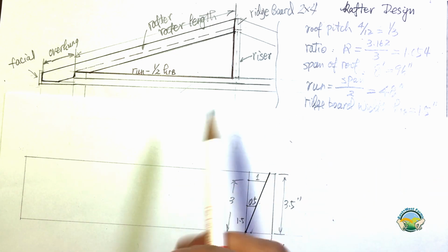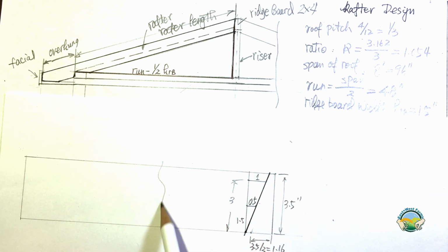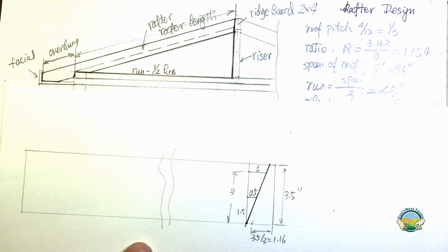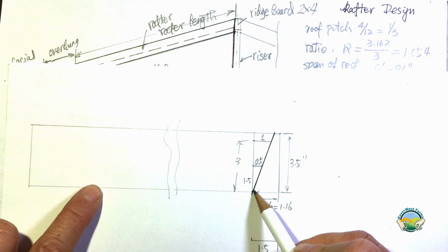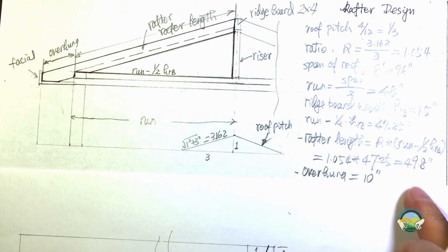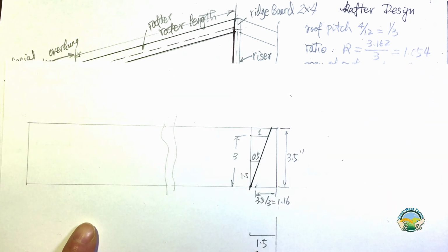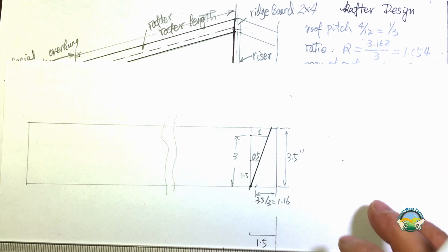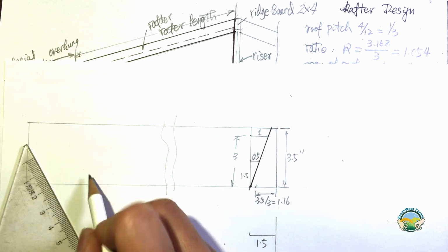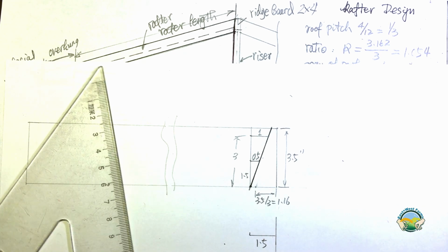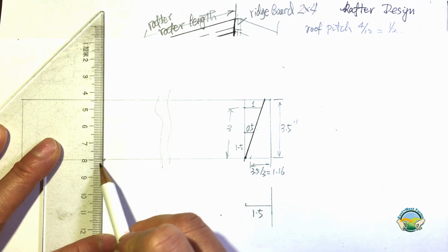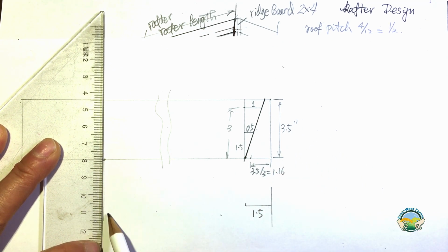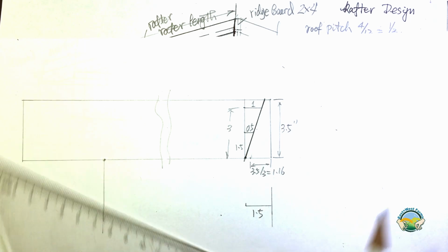In this case, I don't have the length in proportion, so I just assume there's a cut over here just to demonstrate. Since I'm using this as a reference line, from here to the bird mouth is 49.8, and I also have this 1.5 offset. So I would just assume this is my bird mouth. I determine that point by measuring the dimension from my reference line.